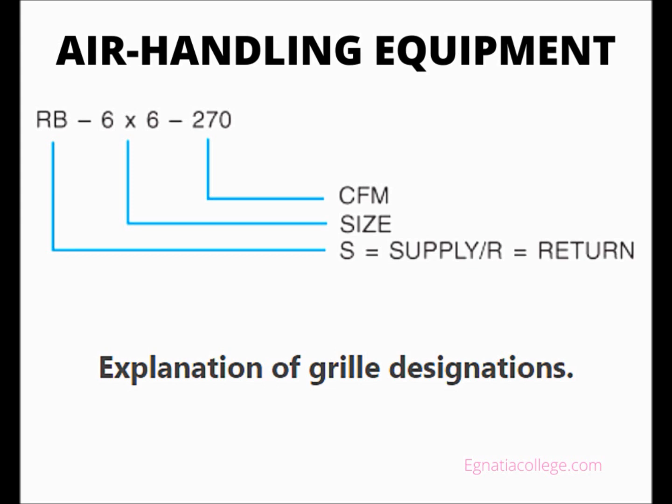This figure explains the designations for outlet and inlet grills. The ducts that carry the air to the roof vent are shown by their outlines and do not indicate their sizes. A square or rectangle with a diagonal line through it indicates where the duct rises to the next floor or the roof. Several notes indicate that ducts rise up to EF- on the roof. EF is an abbreviation for exhaust fan. The number indicates which of the several exhaust fans on the roof the duct is connected to.